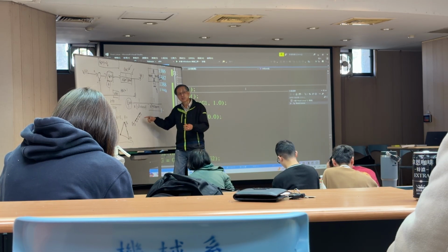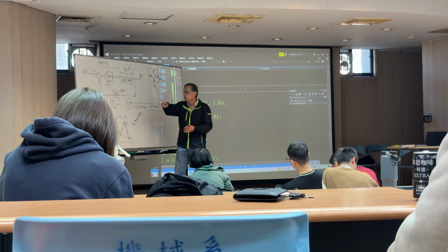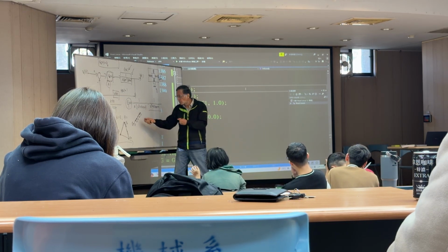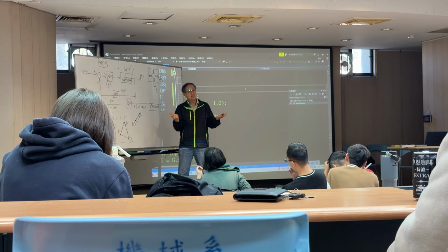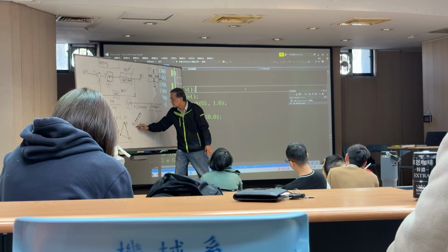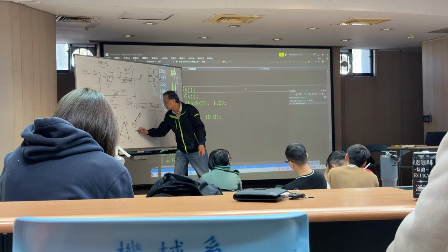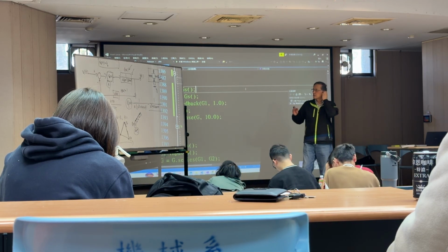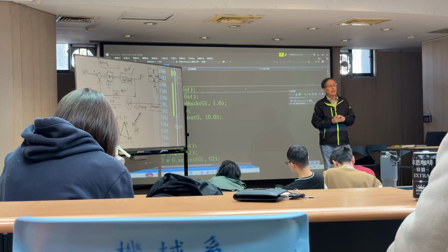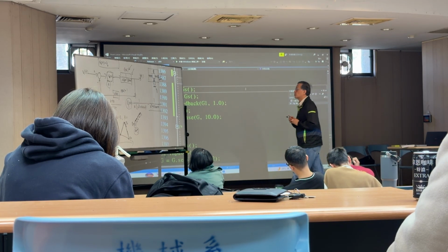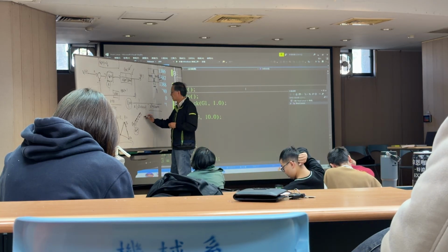Okay? So it doesn't matter whether it's a straight line or a curve, like a Nike hook. You can still divide it into very small delta s. Remember I said? And every time, delta s is decomposed into delta x and delta y, right? So this process is what we call interpolation in the machine tool industry. This is what we call interpolation.